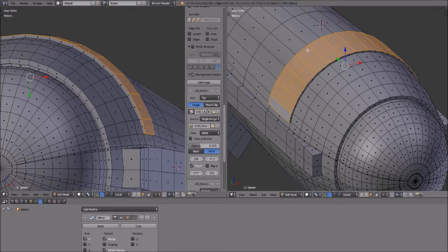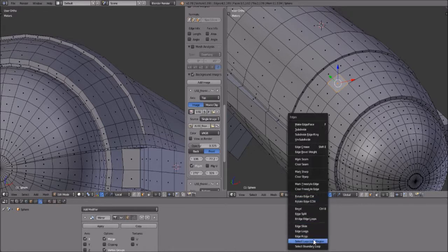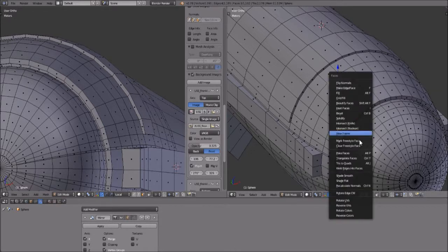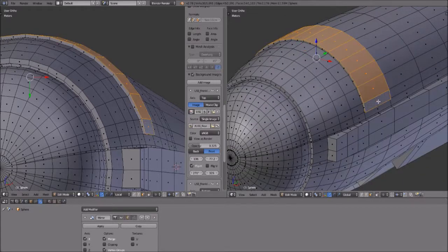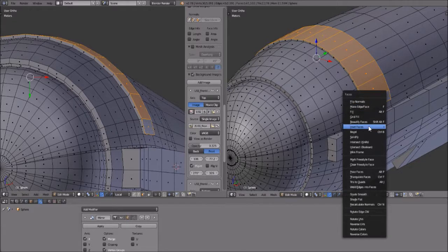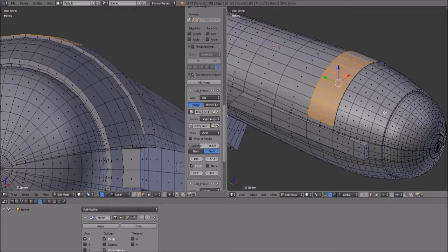Because what I want to do is offset all of these faces inward. Normally on a flat face, I could just click on the face, press E, and then scale it down, and it scales it and offsets everything. I think there is an offset modifier somewhere. For the life of me, I can't remember where I saw it. Inset Faces. Wait, maybe that's it. Let's try that out. Kind of learning something here. Ah, okay, there we go.